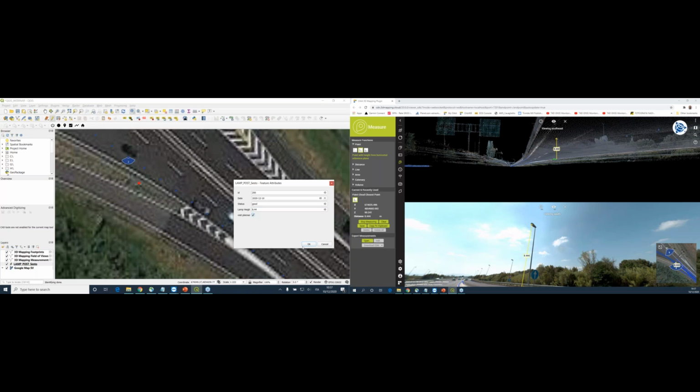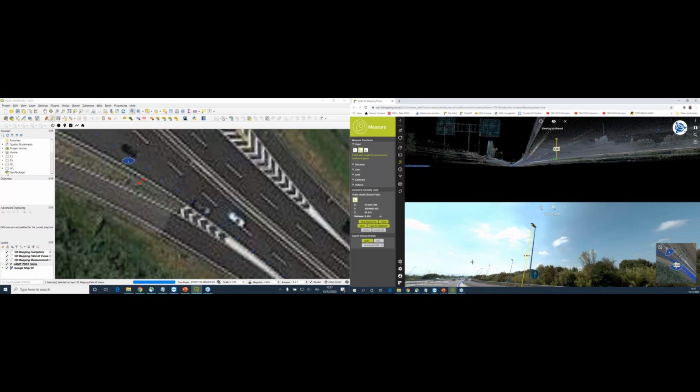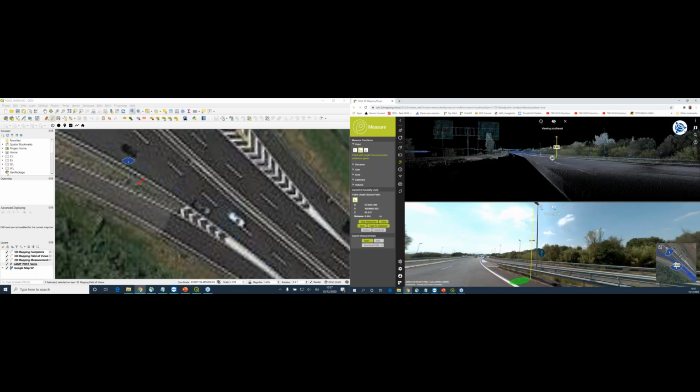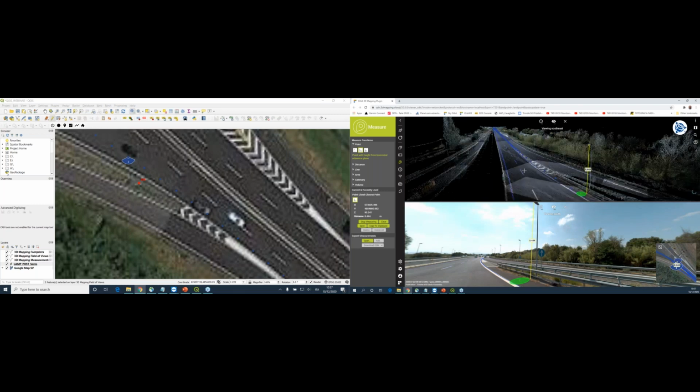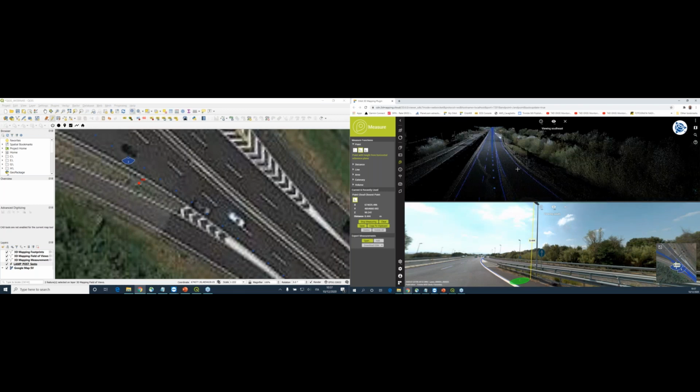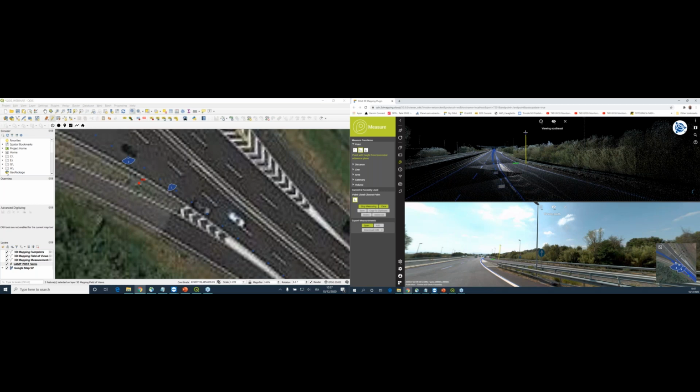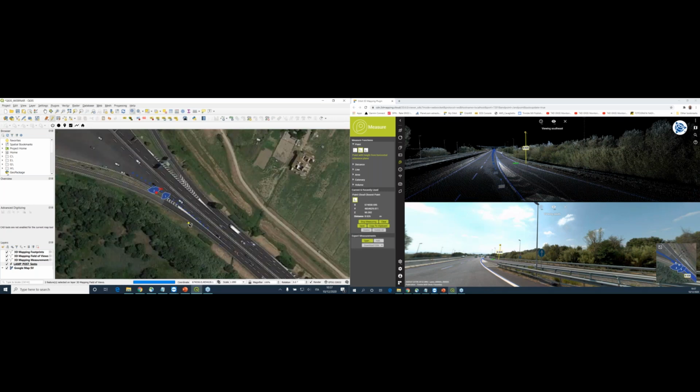So I'm just flagging on this box and saying, okay, this information has been stored in my QGIS layer. Now I can go, for example, to the second pole which I want to visit. Again, the same exercise: I click one point on the ground, then one point on the top. Then I have this one, which is 8.6. I'm going to save this object. This is the object I have been saving into the publication.